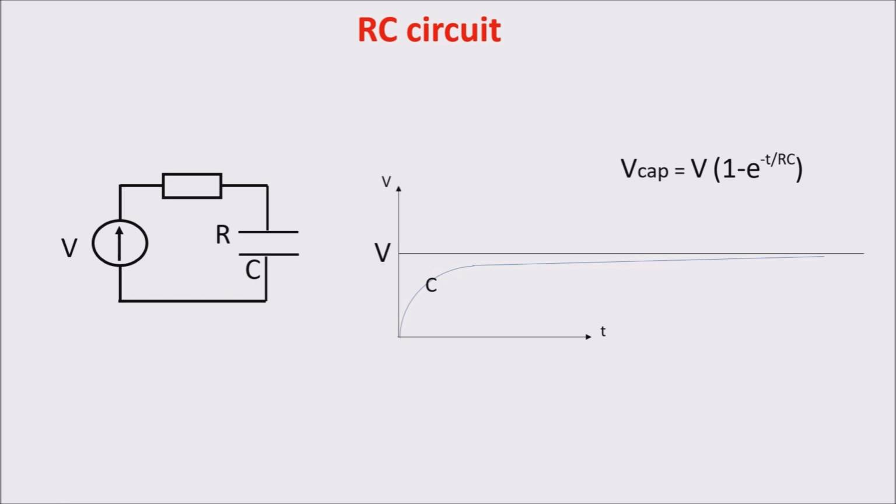Intuitively, the larger the capacitance, the longer the time we need to charge it, because the capacitor can store more charge. So at the end, with larger capacitance, we need more time to reach the same level of voltage, and with smaller capacitance, we need less time to reach the voltage. So smaller capacitors are faster in some way. They reach the voltage faster. Keep in mind this concept because it is important for the frequency behavior. Smaller capacitance is faster to reach the final voltage.